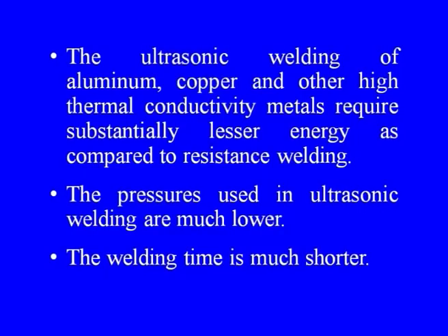The ultrasonic welding of aluminum, copper and high thermal conductivity metals requires substantially lesser energy as compared to resistance welding. As we have already discussed while discussing the resistance welding process, particularly in case of high electrically conductive material, since the resistance of the material is less, therefore, to compensate for resistance, one has to apply higher degree of current to generate the same amount of heat that is needed for melting and fusion of the material.